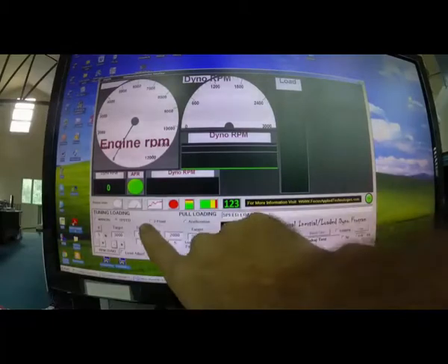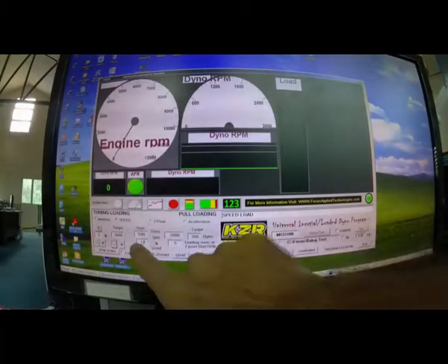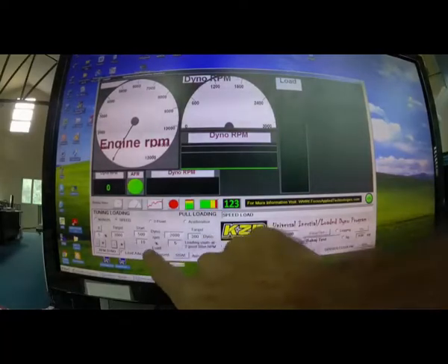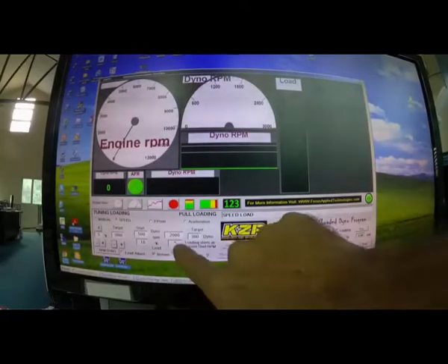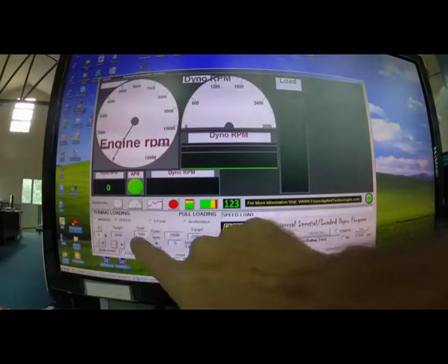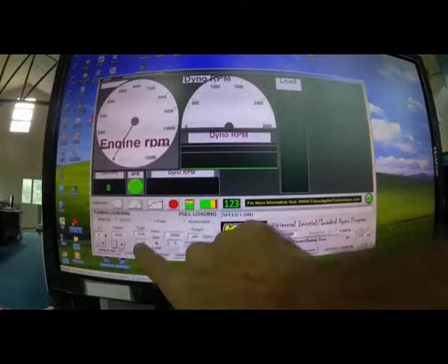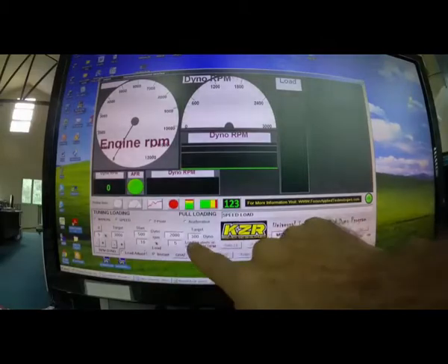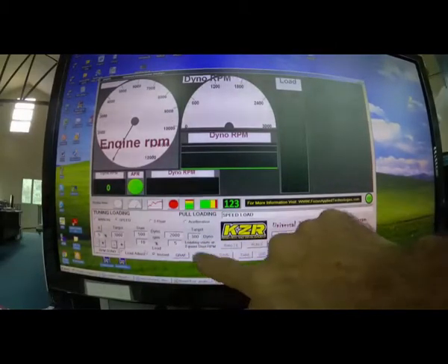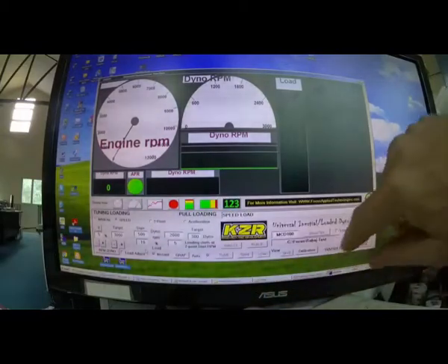There's also a 2-point loading for dyno pulls. So you've got to start and stop dyno RPM, and you've got a percentage load, maybe 10% at the start, 5% at the stop speed, or you can go to an acceleration mode, which starts at the start load and start RPM, but then it increases at 300 RPM per second. So you can set that up over here. So you just choose what your load mode is.